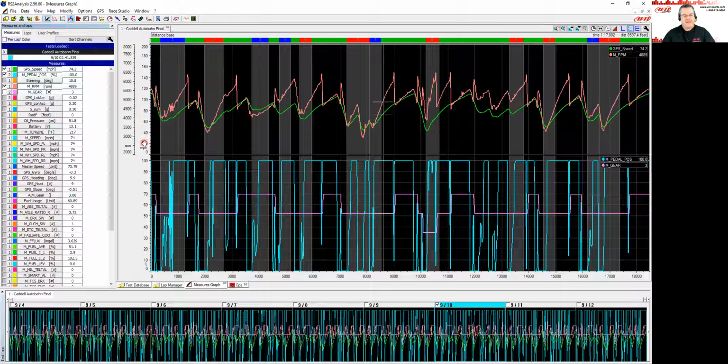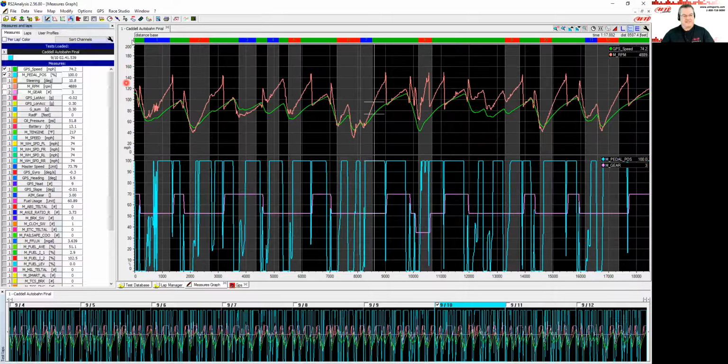So in this case, I've got my RPM and my miles per hour up here with the 2 traces that I have. And if I want to just turn off the RPM scaling, I could come over and click the little checkbox there. And now we've only got scaling for 1 of them. So when you're in the mixed view like we are, the little check boxes are turning on and off the scaling. Of course, clicking on the channel name itself is what adds it to the main window. And then the numbers move you around, so you can put it where you like it.